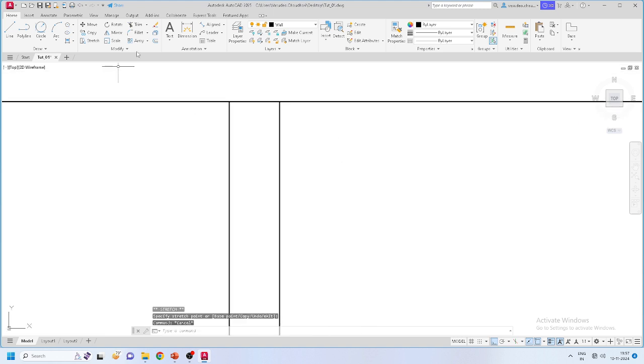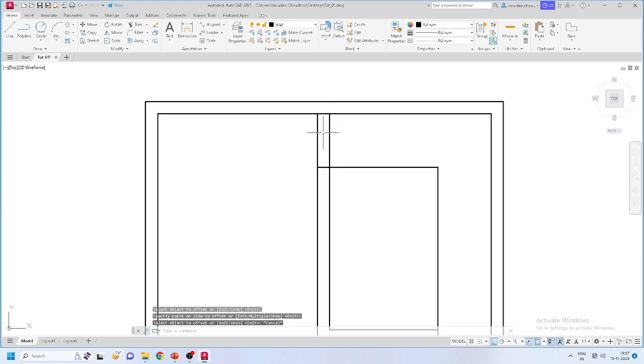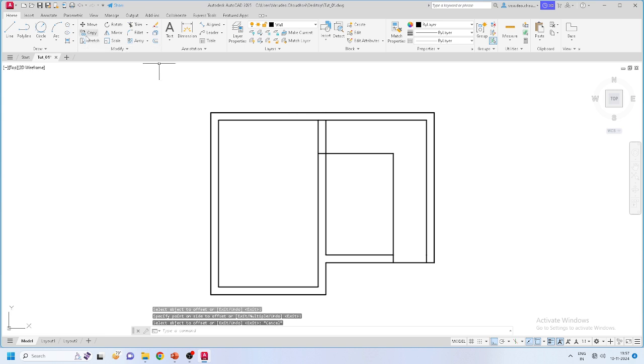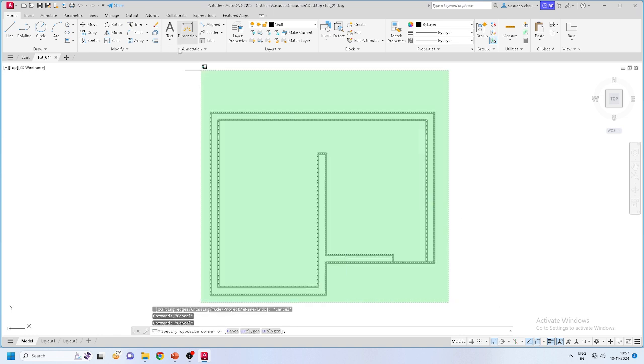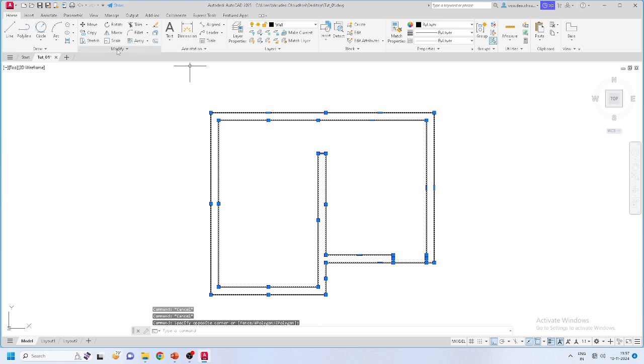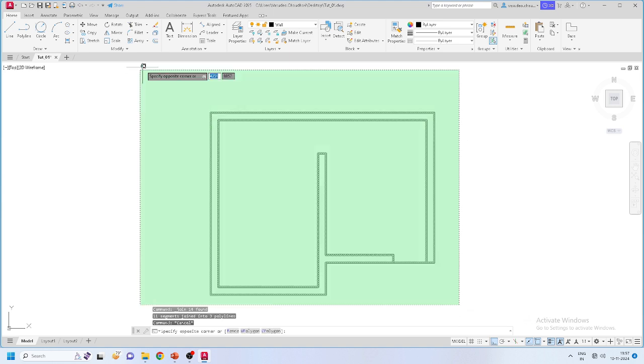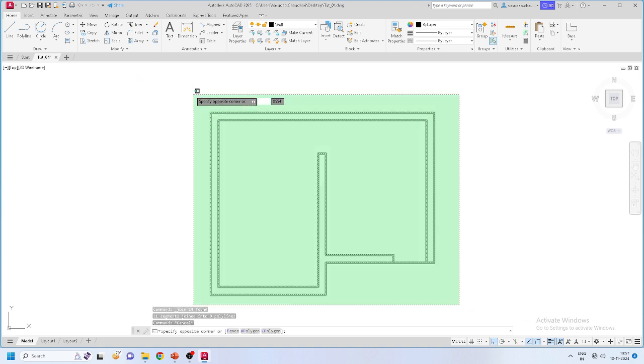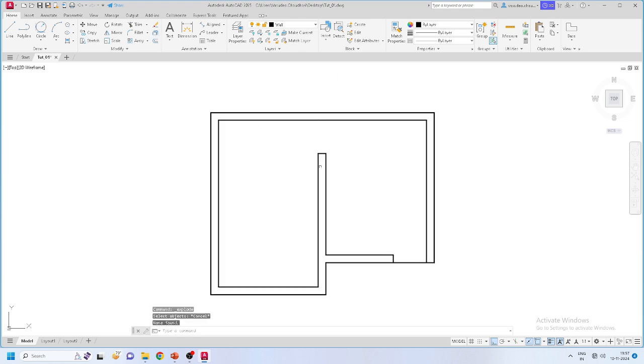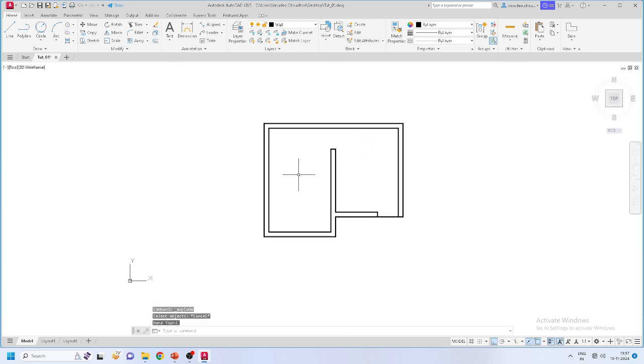And then offset say again 1000, enter, and then that's my polyline. Then trim. So I'm trimming this part. Even I have to trim this line and this line, right? So maybe first of all let me use some command. I am joining all the lines which are close together, and then again I am exploding them so that each line becomes separate, right?